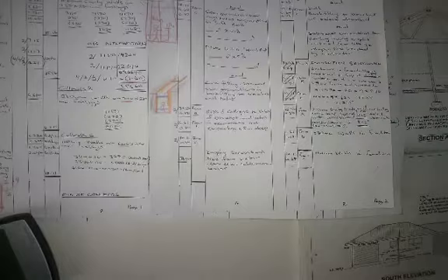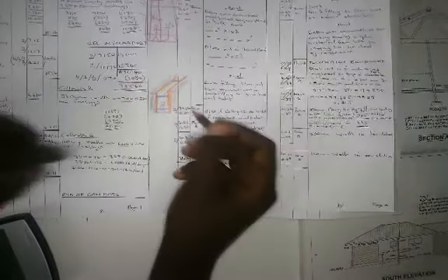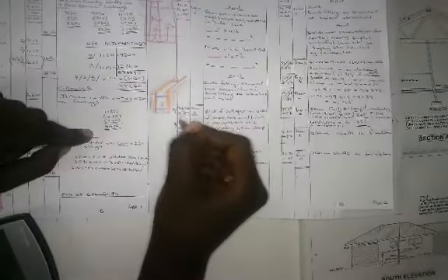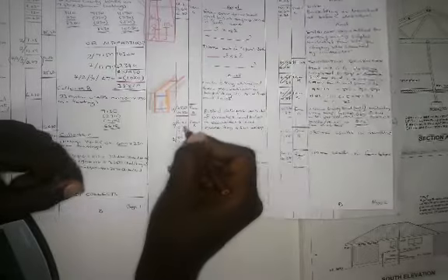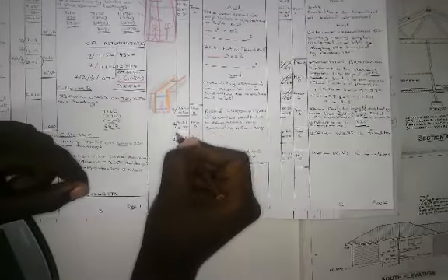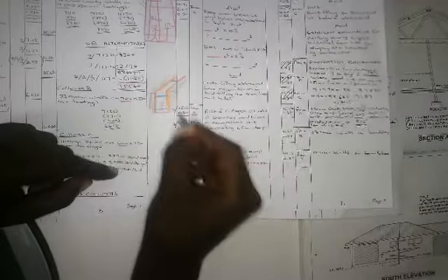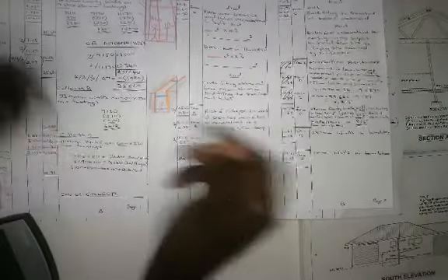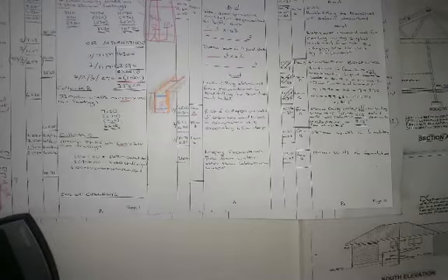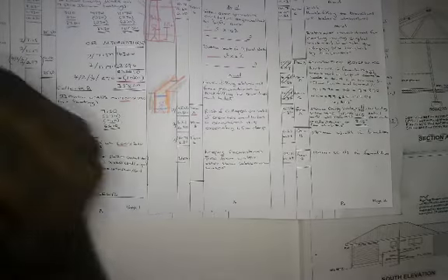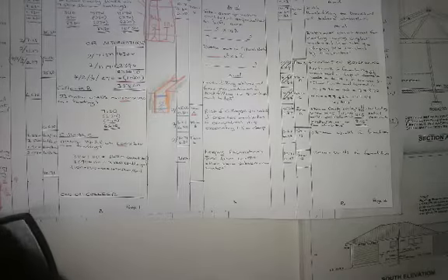Okay, I'm hoping this makes it a bit more clear. This is your trench, a person is working there, so we are ensuring that the soil doesn't collapse into the trench, right? So again, take a center line times the depth of your trench, which is 0.8, times two sides, this side and that side. Same thing on your excavations for your 230 wall, 6.61 times the depth and both sides.